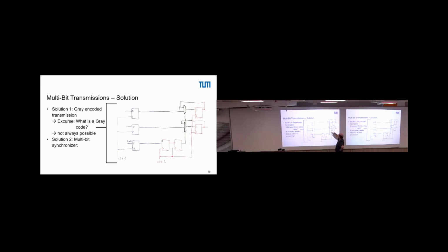And therefore we do not need a synchronization circuit here, but we only put a multiplexer. And this multiplexer is configured so that as long as the enable signal did not arrive, we store some data here. When the enable signal arrives, then we enable here the input path, this one here, the black one, and take in the valid signal from the data path into this flip-flop.